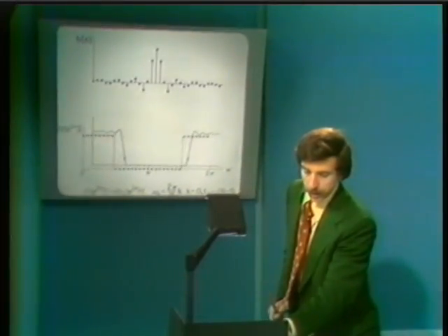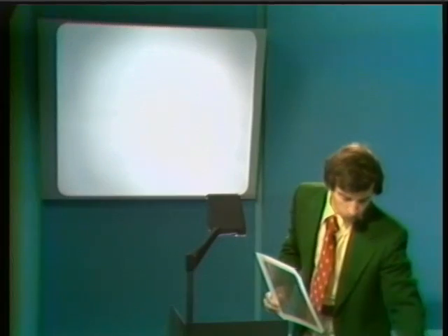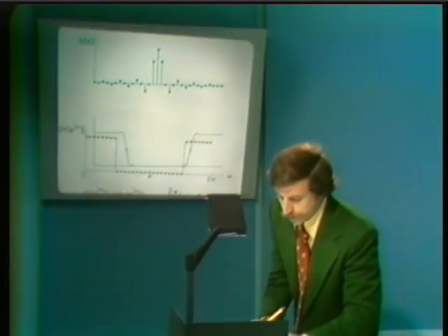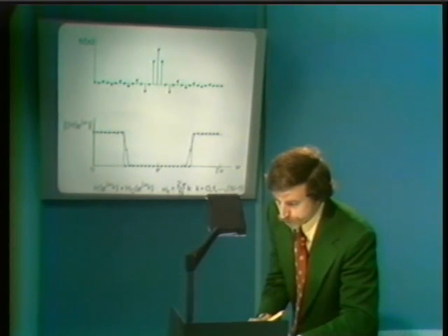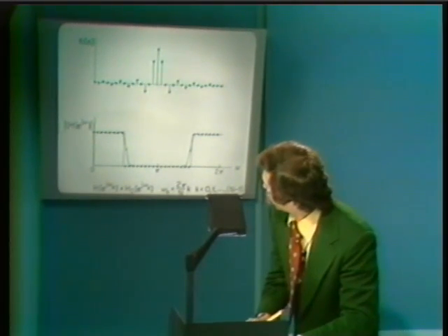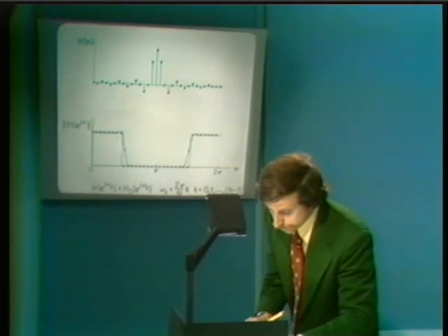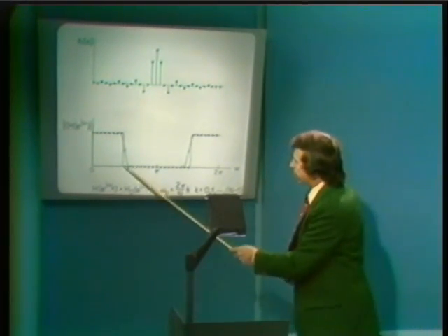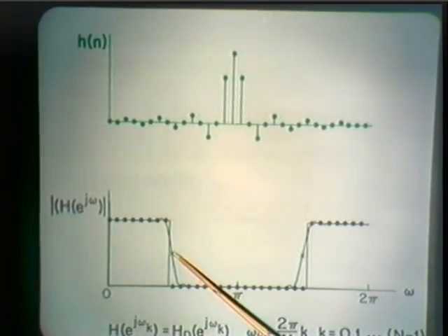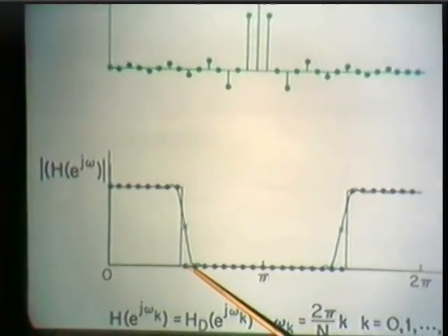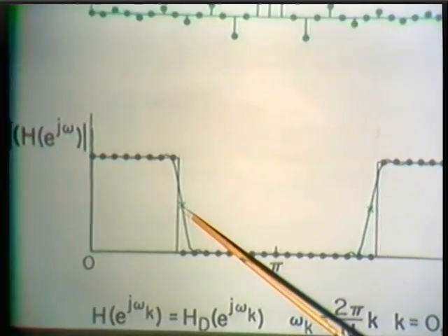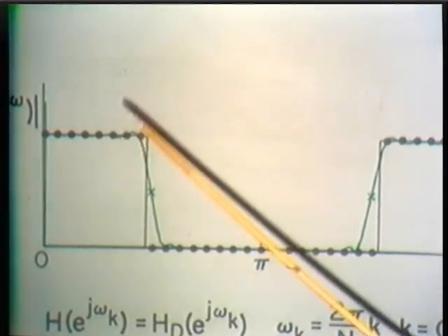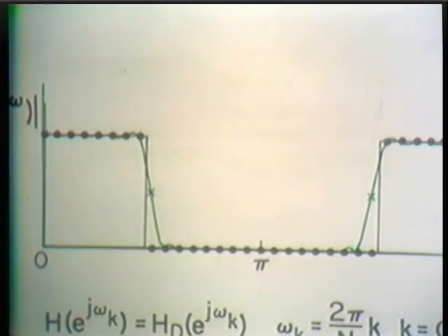And let me illustrate that with this next example, where in this case we have moved the transition point up somewhat further, so that whereas in the previous case the transition point was someplace down here, we've now moved it farther up into the transition region, closer to the passband, and the passband ripple has become correspondingly smaller.